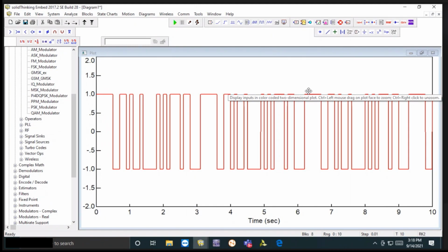Okay. So here we can see that we have the input signal. It is of bipolar behavior, going from -1 to 1, right? And why are we taking this one? Because we are talking about the QPSK, and here we are actually going to add two PSK signals, for the odd place bits and the even place bits, and then we'll sum them up.